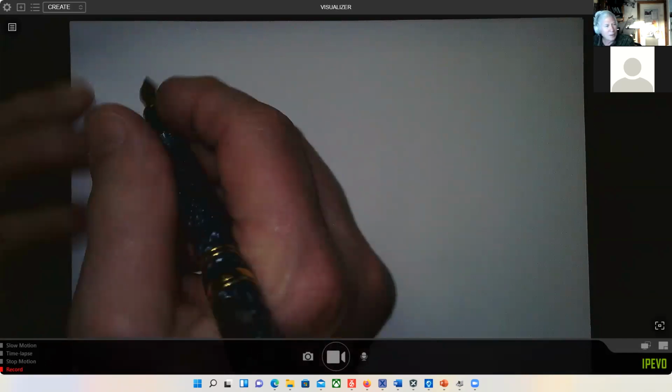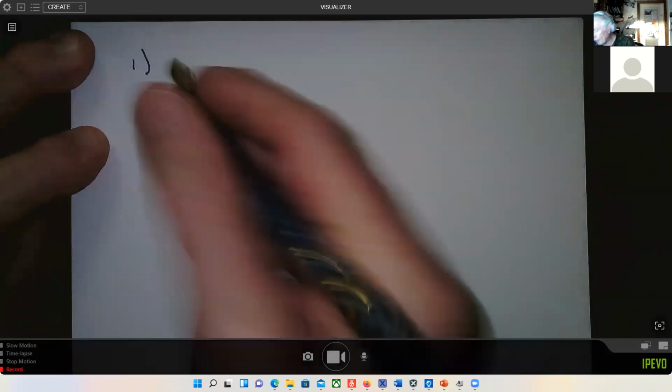Anyway, okay. So the first thing, poll a bit. Why would we want to poll a bit? And what does that even mean? So we have a bunch of GPIO ports on this chip, and it is a 20-pin chip, and 2 of the pins are power and ground. 1 pin is the master clear pin, which can be an input, but if you use it as an input, then you can't use the debug features of your integrated development environment. So we want to use it with our programmer attached, and with our programmer attached, we're going to use the master clear pin as a master clear, so it won't be an input.